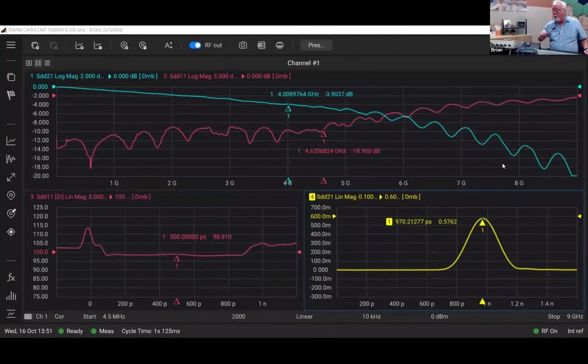It's a little hard to see, but here at the top there's a 100 ohm differential line, and it's very, very small traces. And I've hooked to the board using little SMA semi-rigid pigtails, which hopefully you can see on my camera. And then I've just connected that to my 4 ports on my VNA.